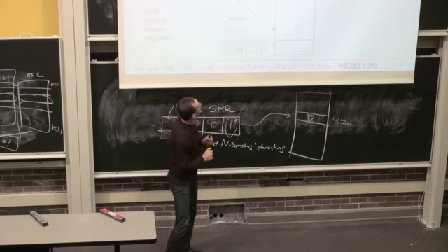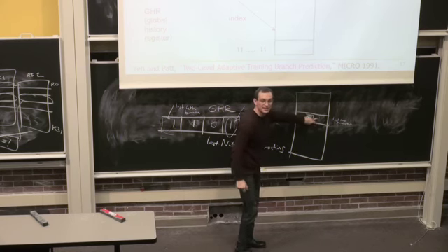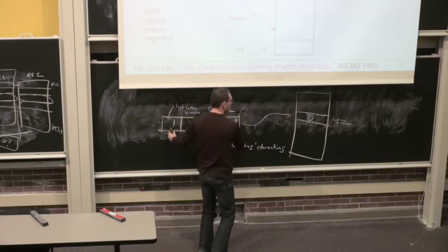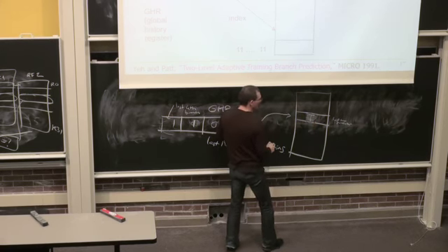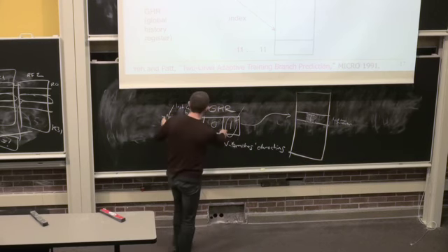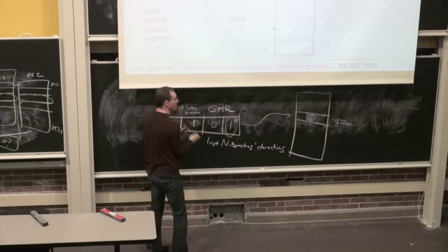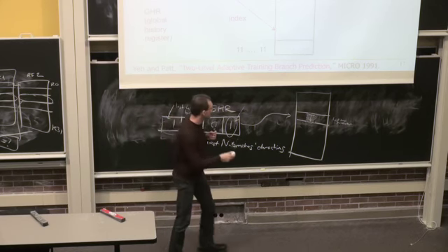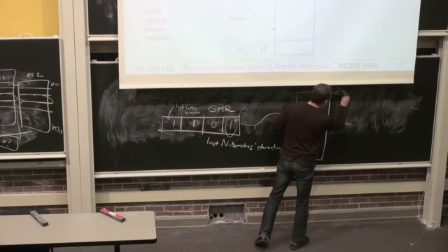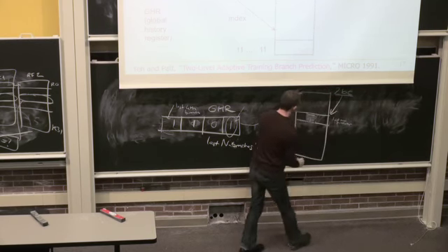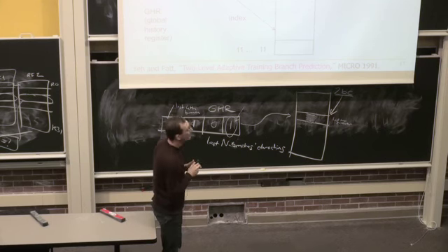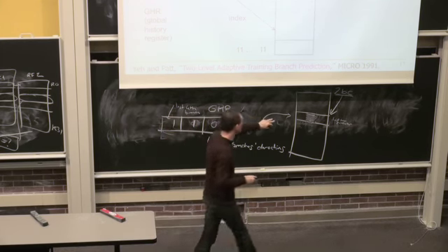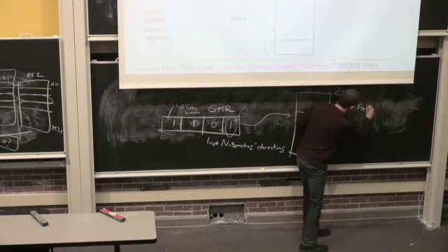And of course, you could still have hysteresis for this particular history as well. The outcome could be always taken, for example. But what if the last time you see this history, the outcome fluctuates? You don't want to change your decision. So you can also have 2-bit counter predictors in this table. Does this make sense? Any questions? This is called a pattern history table.